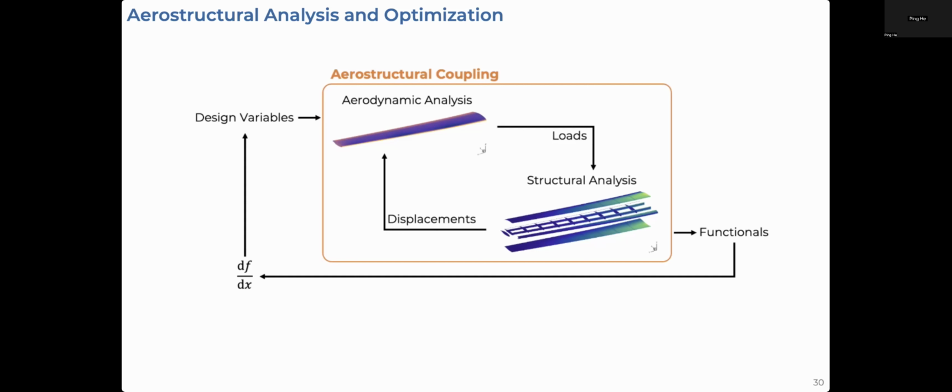For our case, we remove the nacelles and we model the propellers as actuator zones to simplify the geometry and the optimization problem. We'll have three different scenarios. We'll have a hover scenario that is purely structural to make sure that the aircraft is structurally sound. And then we have a cruise scenario and a maneuver scenario, which ensures that our vehicle can sustain a specific 2.5G maneuver when in flight. For the structure, we use this methodology where we remove the nacelles and we connect to our propeller locations using rigid body elements in our structural solver.